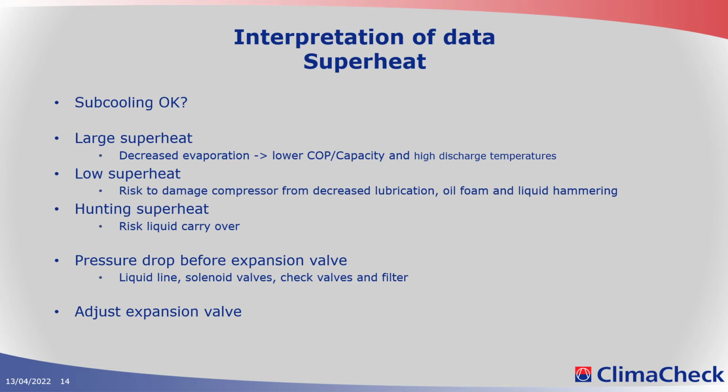Of course, it can be a question of a shortage of refrigerant, but it can also be a pressure drop in your filter dryer. There can be a solenoid valve before the expansion valve that's not working correctly. There can be a blocked strainer. There can be many reasons why your superheat is increasing that are not the expansion valve itself. It's that it doesn't get the chance to run properly.